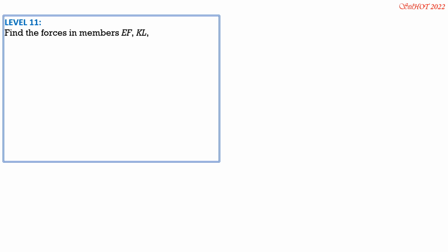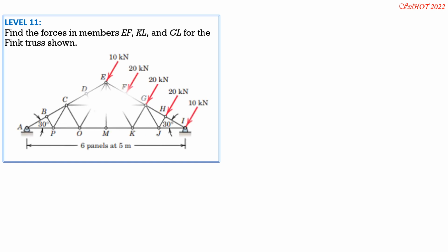Find the forces in members EF, KL, and GL for the Fink truss shown. So we have a compound truss, and let's apply method of sections this time, or combinations of method of sections and method of joints if necessary.